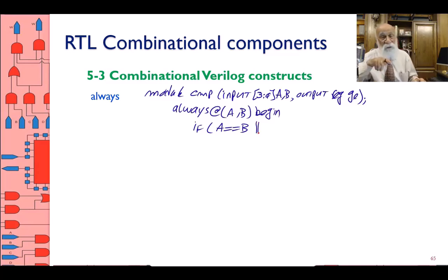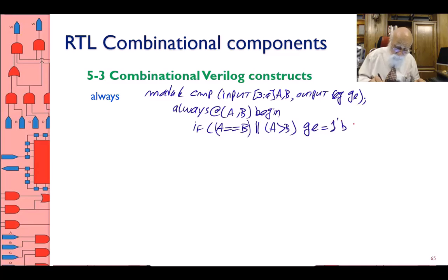Logical or we have the, let's see, we have the comparison or the double or is, skip my memory right now. But anyway, if you want to say if A is equal to B, you do two equals. Or if A is greater than B, then GE equal 1'b1, else GE equal 1'b0,